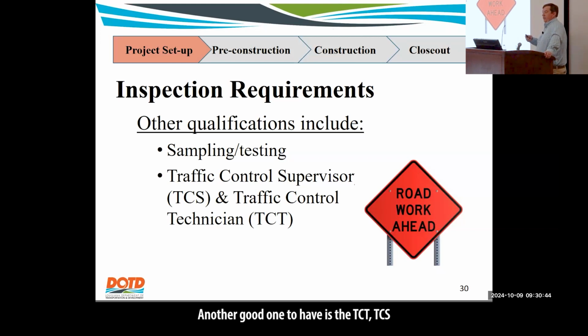Another good one to have is the TCT/TCS. That's your traffic control technician, traffic control supervisor. We typically make all of our inspectors have it just so they're aware of the requirements on a job, to make sure everybody's safe. This is the number one thing. I'm sure y'all saw recently, we had a MAP truck driver get hit. He had everything set up properly, everything was done correctly, and he still got hit.